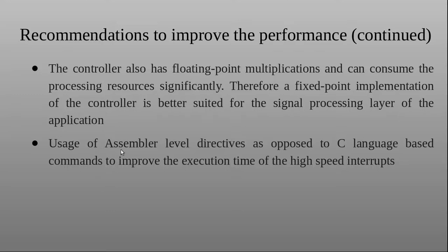Also, using assembler level directives as opposed to C language based commands to improve the execution time of the high speed interrupts can also improve the performance, because assembler directives are way faster than C language based commands, because of the cross compiler tool chains involved and non-optimality in the way C is translated into assembler directives.